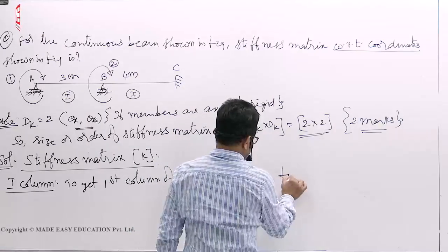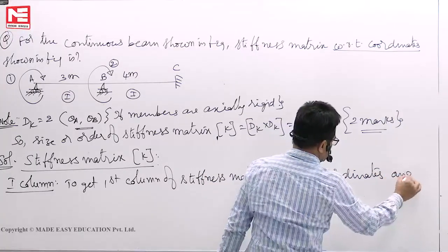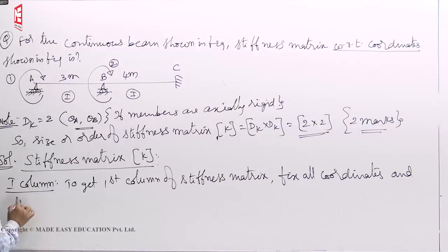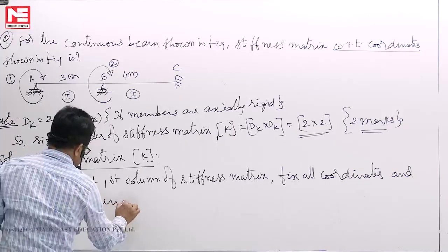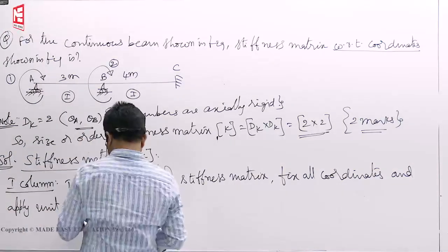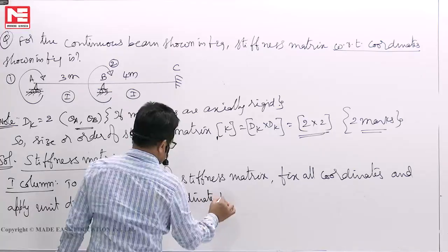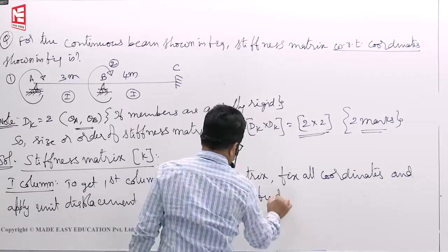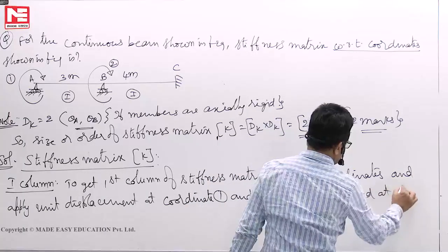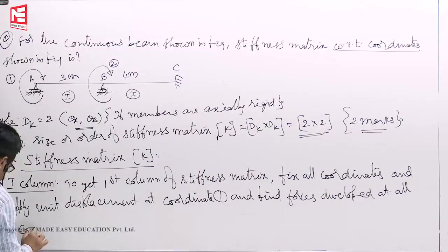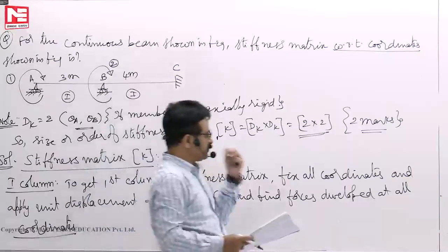Fix all coordinates, this is what I told you. Fix all coordinates and apply unit displacement at coordinate 1, and find the forces developed at all coordinates. This is your first column.